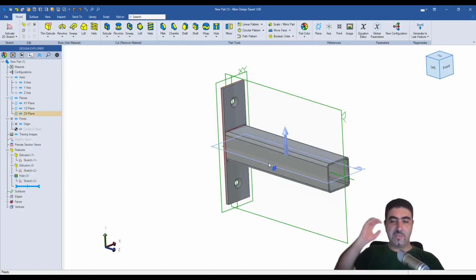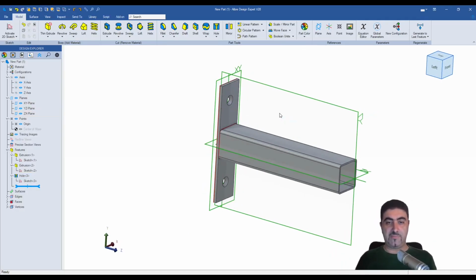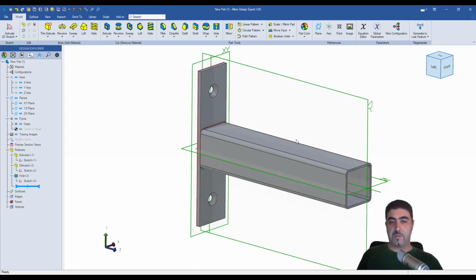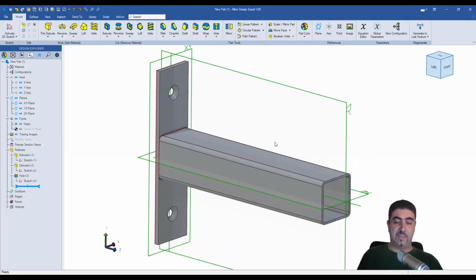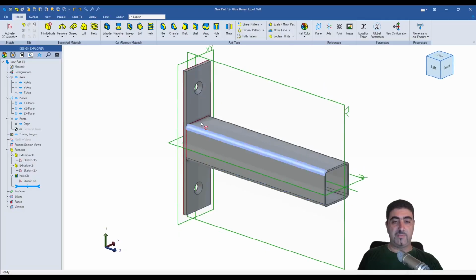And this is the part on which I'm going to conduct my FEA study. Now, it is very often that we simplify a part that we want to study in finite element analysis. And this is what I've done here on purpose, right? Not as a second step. So in reality, this is not one part, it is 2 parts, and it would be welded together. So it would have a weld bit here and here on the bottom, a fillet weld.